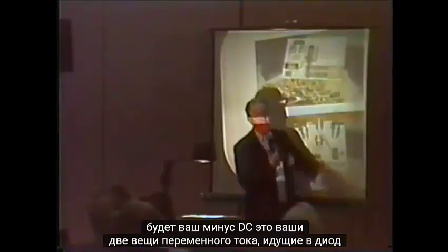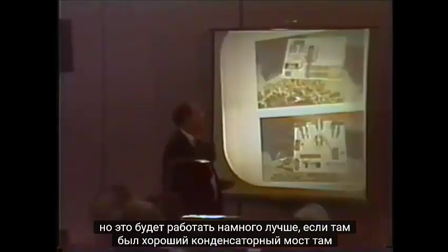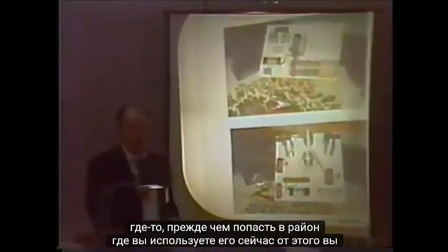These are your two AC inputs going into the diode bridge. This particular one is set up so that you get 60 cycles at a usable level, where you can just plug it directly in and you're off running. It's intended to go directly without the capacitors and other things, and it works fairly well, but it would work a lot better if there was a nice capacitor bridge in there somewhere before you get to the area where you're using it.